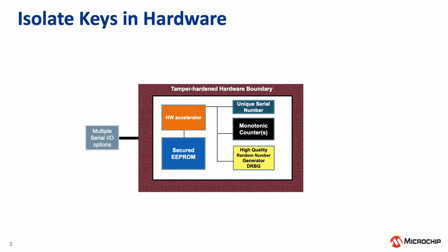And on top of all of that, you have another value in physically isolating that secure space specifically for the key from the rest of the system. You also have a logistic reason. It's customization. You have a key, you have customization. You have customization, you have a supply chain challenge. It's cost in the supply chain. So it's more cost effective to customize a tiny piece of your system, the secure element, versus handling a fully customized system that you're going to have to ship across the world. Much more cost efficient from that standpoint. That's why it's been a practice to use those discrete architectures.